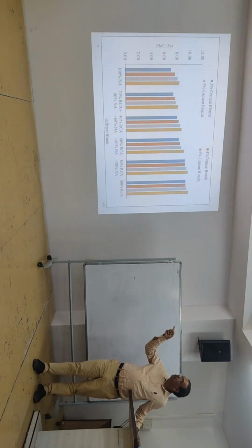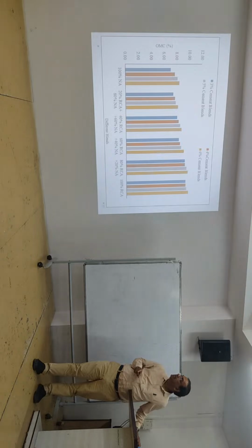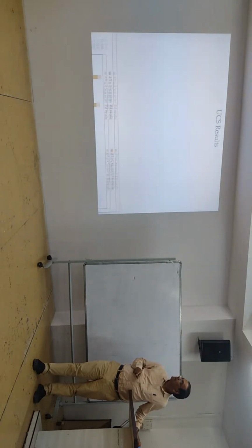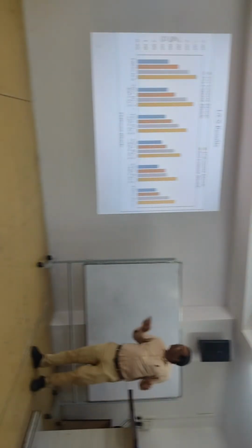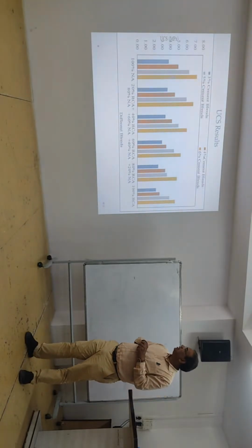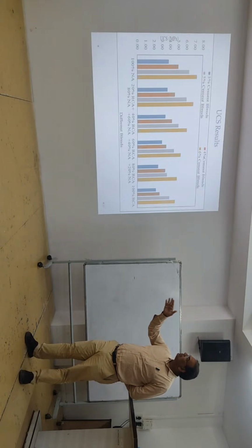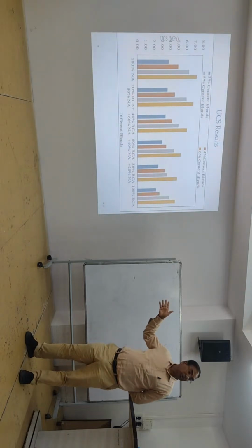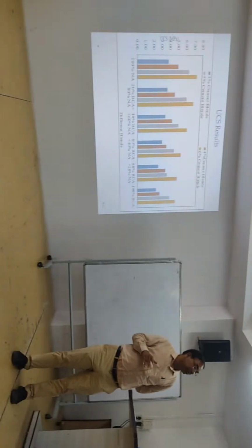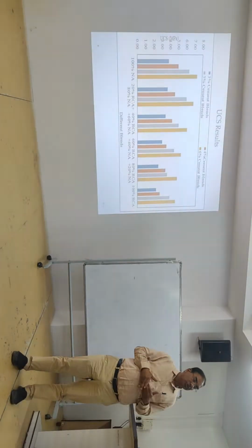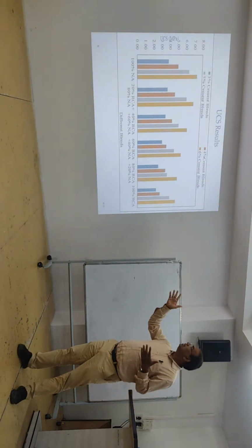So 8% to 10% is what we can see it will increase. Then UCS, as you can see how much it increases. Natural at 100% is not so bad. Almost, you can see, with 3%, 6%, but the cost will increase. They are putting in cement, 6% cement, so certainly your cost will increase, but strength wise it is not so much.